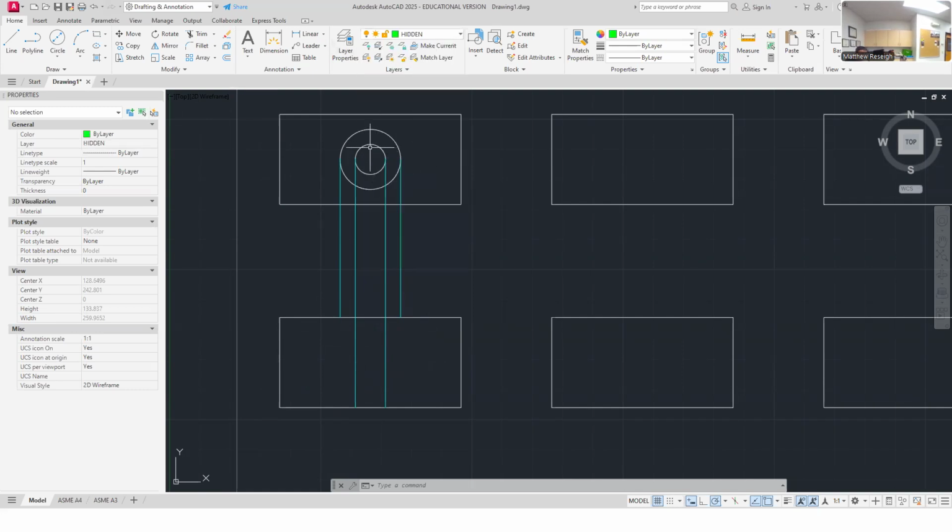But in this view, because the part has been bored in the middle, in the front view, I can't see it. It would be like I need X-ray vision to see what's going on if I actually turn that block 90 degrees from the top view and looked at it as a front view. I wouldn't be able to see it. So I have to show it in this view as hidden line work, and so that gives us kind of X-ray vision in our drawings.